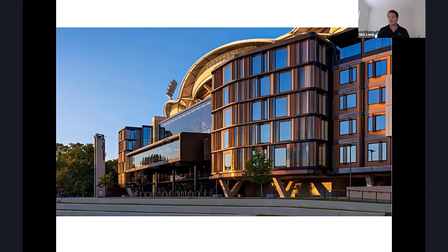And then I guess the key changes and advantages that CLT brought was the lightweight structure. Adam touched on the acoustics as well, but there are also some vibration issues with using a lightweight steel structure. A lot of them were key design outcomes, but also constructability and timing. It was always going to be a tight program, but the CLT definitely helped achieve that program in the end.